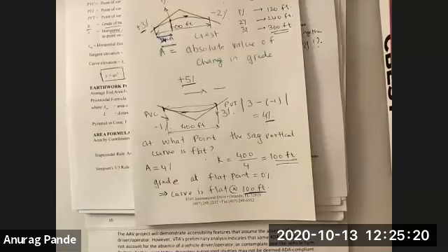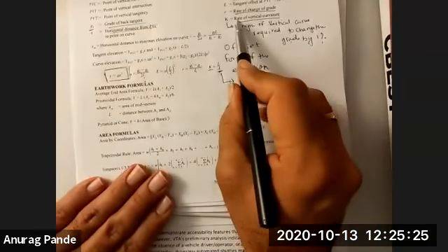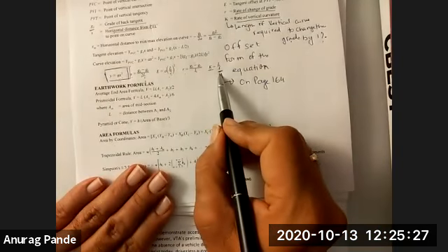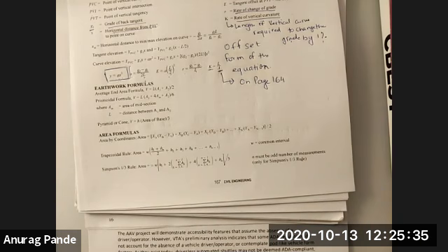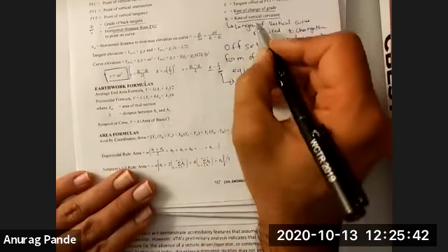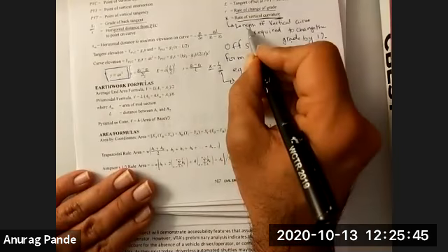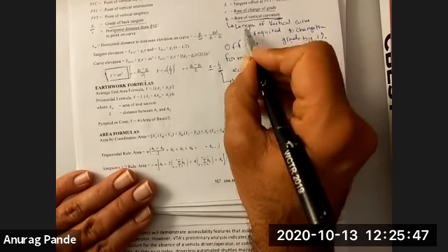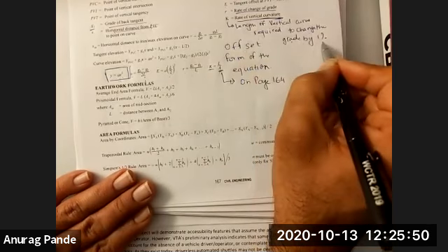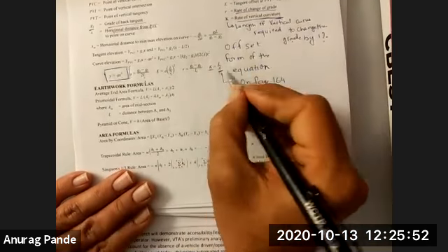Okay? So that's basically the idea of how this formula given here, K equal to L over A, could be very helpful to you in figuring out where the vertical curve is flat. You can do so very, very quickly, but you have to know the concepts involved here. You have to know that when the curve is flat, the grade is 0%. And then how do you figure out the rate of vertical curvature? You have to know the clear definition of it: it's the length of the vertical curve required to change the grade by 1%. And A value is defined on page 164.